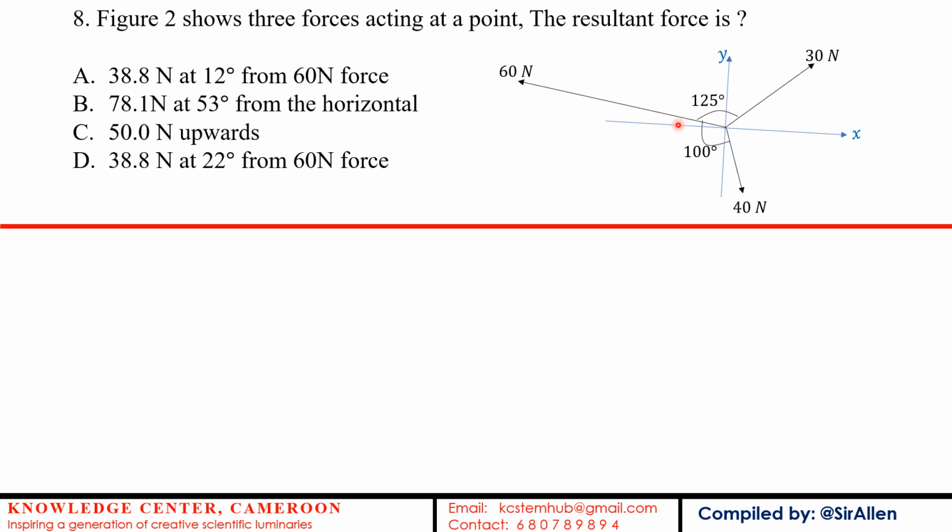How do you get that angle? You cannot. So what you need to do is draw a reference axis from a particular force. If I read through these alternatives, you notice the examiner is talking a lot about the 60 Newton force. So I have to wipe this off and draw a reference along the 60 Newton force. This 60 Newton force is my x-axis and then my y-axis somewhere here. These have to be perpendicular to each other. We understand that. Now we can solve the problem.